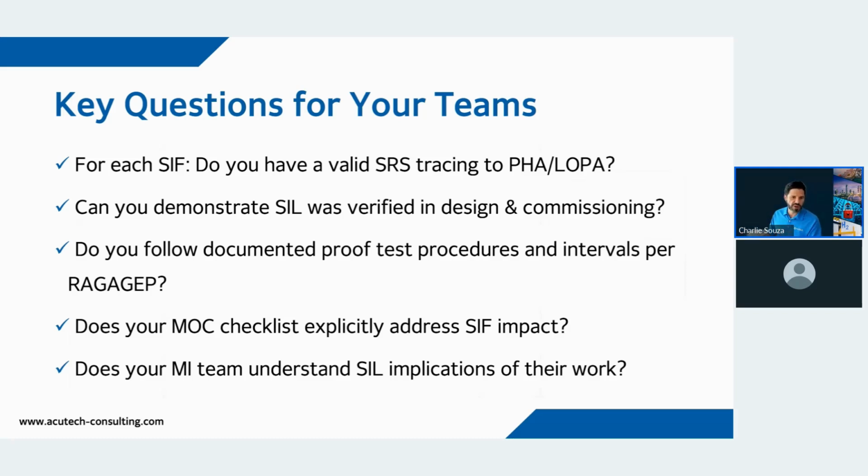Does your MOC checklist explicitly address SIF impact? Do you have a checkbox there? Do you have the functional safety expert on your team? A functional safety person, one of the approvers, one of those signing off on that MOC, to make sure that it would be his job to make sure that his systems are not affected. And that those on my team understand the implications of their work.